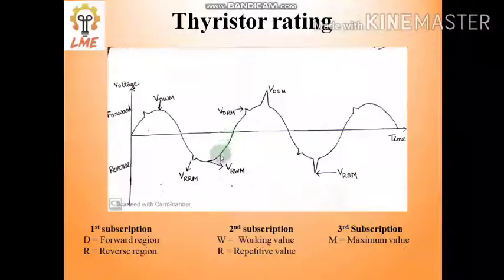In this way, we can find all the values from the data sheet. Whatever circuit we are using, we have to find the practical value of VDSM, meaning the circuit value of VDSM should not exceed the value of the data sheet. So in this way we can use our Thyristor as per the rating and our desirable rating. After all this checking, if we buy and use the Thyristor, the Thyristor will never be damaged.